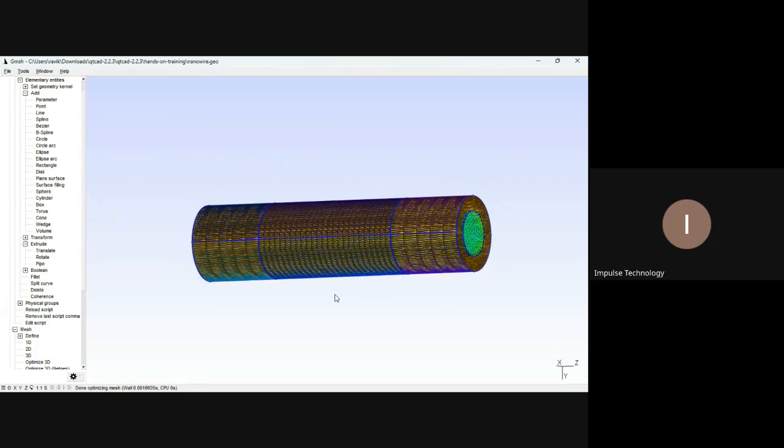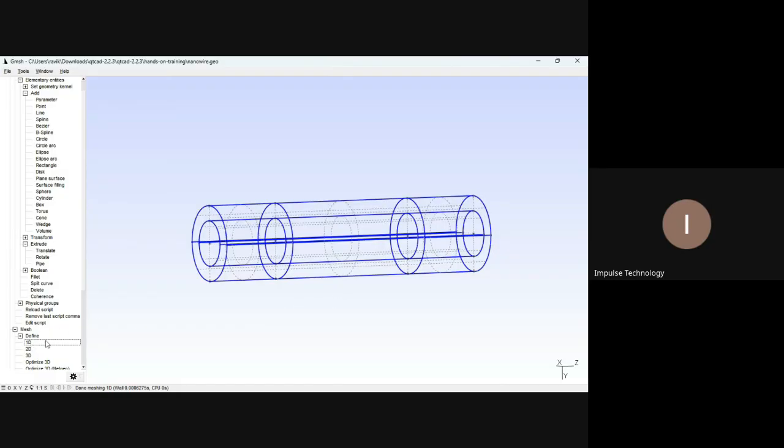Now we have to assign the physical group here. You have to assign the drain band, gate band, source band, and the drain oxide volume, drain volume, source oxide volume, channel oxide volume. We have to assign the physical group now. For that, again click on the 1D structure.